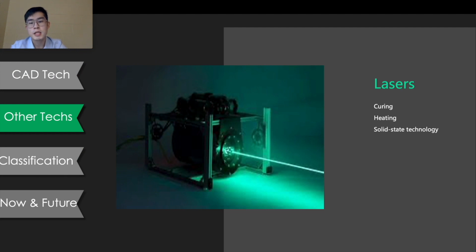There are two kinds of laser processing used in AM. They are curing and heating. With photopolymer resins, the requirement is for laser energy of a specific frequency that will cause the liquid resin to solidify or cure. Usually this laser is in the ultraviolet range, but other frequencies can be used as well. For heating, the requirement is for the laser to carry sufficient thermal energy to cut through a layer of solid material, to cause powder to melt, or to cause sheets of metals to fuse.